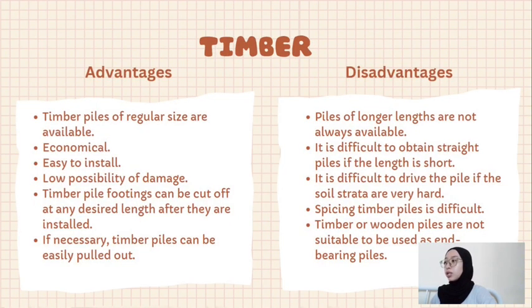Okay, first one, let's look at the timber. Timber piles are the type of pile foundation that are placed under the water level. They last approximately 30 years. They can be rectangular or circular, and the diameter or size can vary from 12 to 16 inches. The length of the pile is usually 20 times the top width. Additional strength can be obtained by bolting fish plates to the side of the pile.